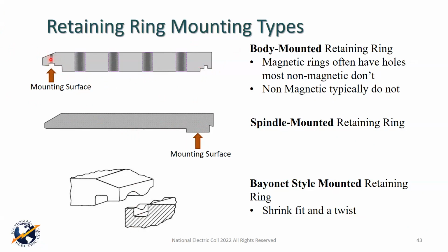And how you get this off is as you heat it up, I think it's a 1/4 cap screw that comes down, and there's ways you can determine where the split is in the ring, and you start opposite the split and work your way around so that the snap ring gets pushed down into the hole. So when you heat it up, it'll slide right off, and then you take the snap ring off.